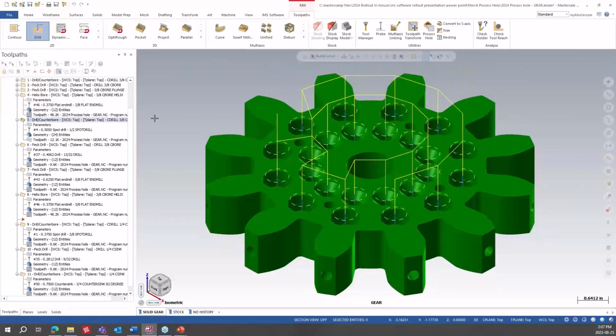There is no way to apply that before exploding it. So you'd need to explode it before you'd be able to move those operations or put all the center drills first. Because I know what you're after. You'd want all the center drilling first and then the other processes. So this would be the way that you'd do that: explode the process and then drag one center drill into the next, basically.